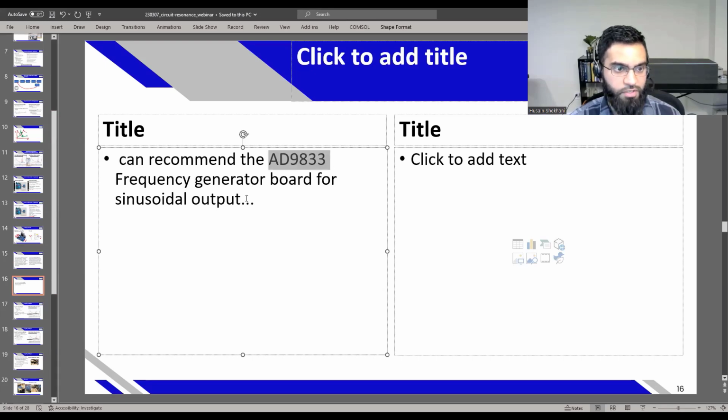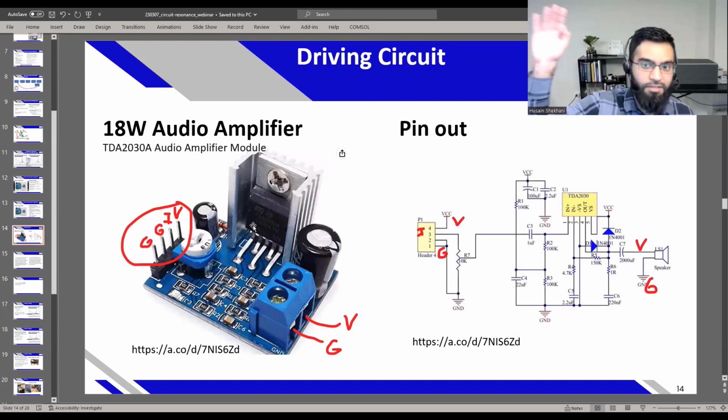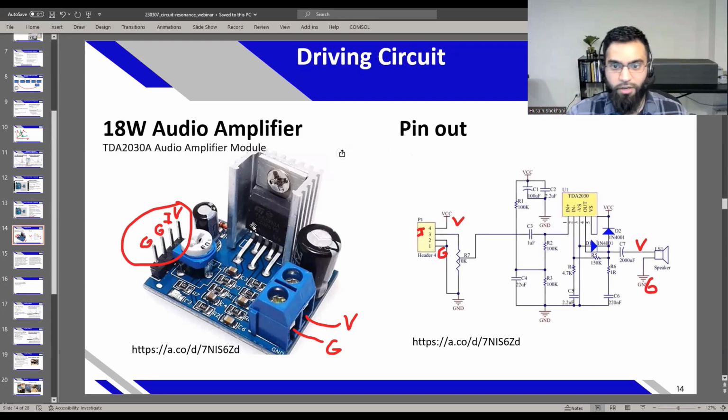But yeah, a sine wave is going to be better for the envelope amplifier because you'll get a lot less garbage out, and you're going to dissipate a lot less energy driving these random harmonics, like driving some capacitance off at 300 kilohertz. It's draining a lot of current maybe, but it's not doing a whole lot of anything. So I like that. Thanks for that recommendation. And how good is the sine wave? Pretty good, not too bad. That's all I'll say.